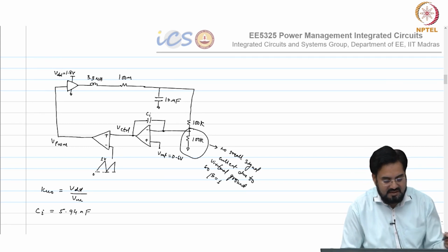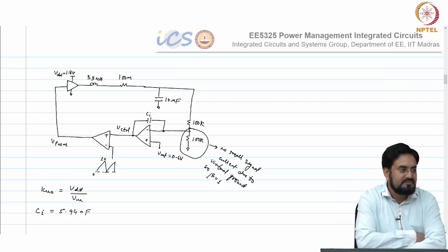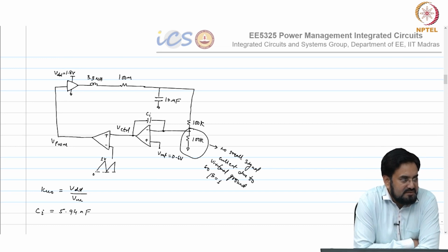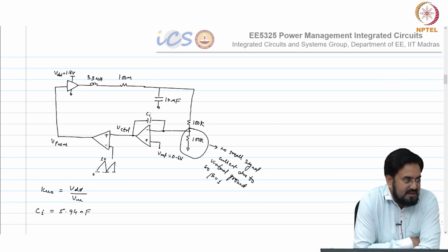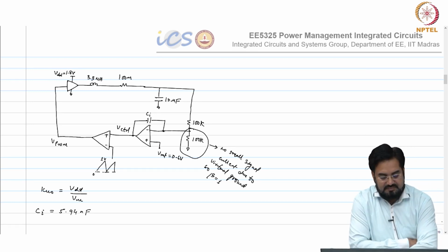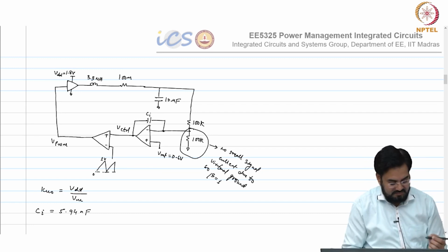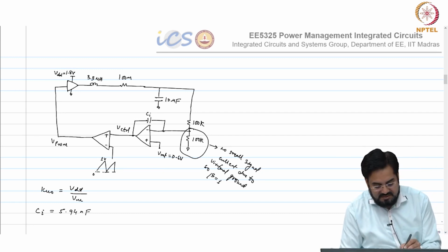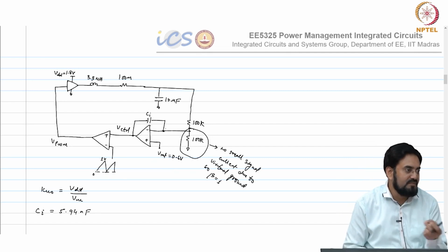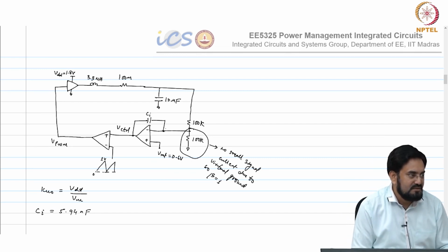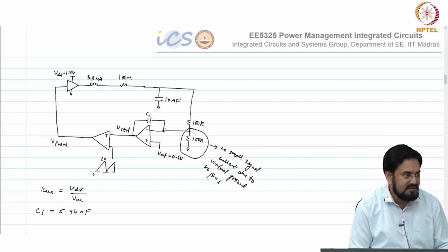So, when you go external, you usually choose mega ohm also, okay, but on chip you cannot put, like, you can do 1 mega ohm, we do actually, but tens of mega ohm is very unlikely, this will take a lot of area, okay. And the higher the value is, you are making that node basically weaker, so it can pick up noise very easily.